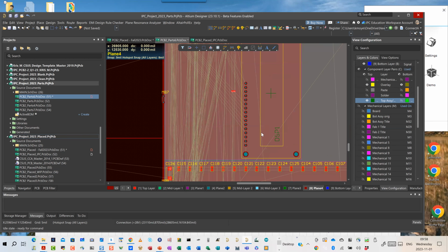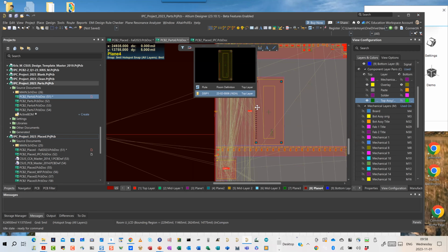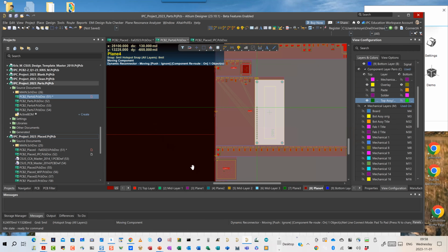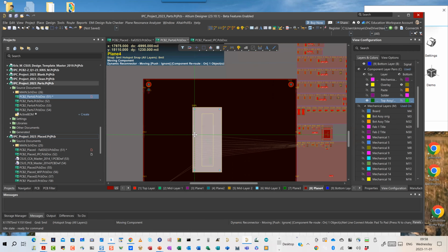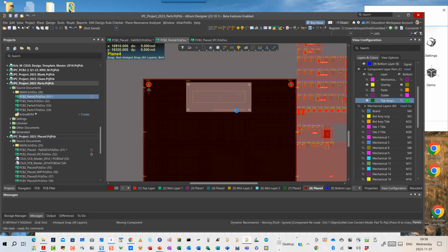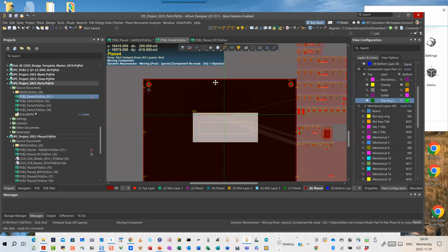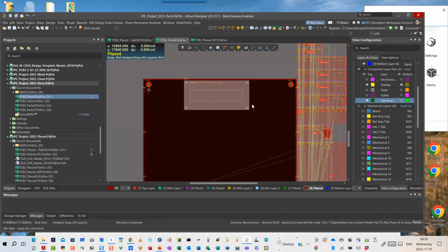In my newer ones, you saw how I also put text orientation, basically meaning when you're placing something like an LCD display, that's got human readable characters, it might seem from a routing point of view that this makes more sense in this orientation right here, because my pins are at the bottom and I can just route straight down, except the characters of the LCD would be completely upside down. So be sure that you're also taking into account the text orientation and human readability when you're placing that part into your design, even though my routing is going to be a little bit more challenging right here.